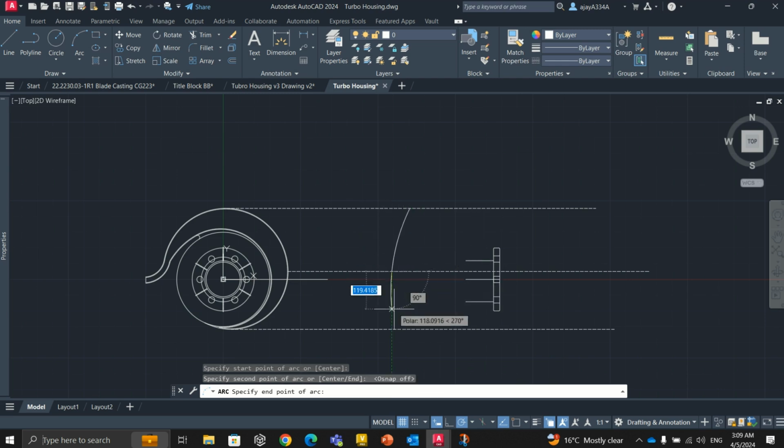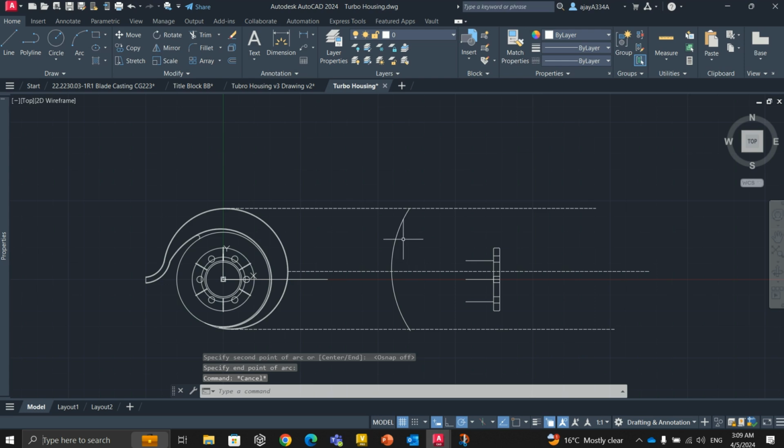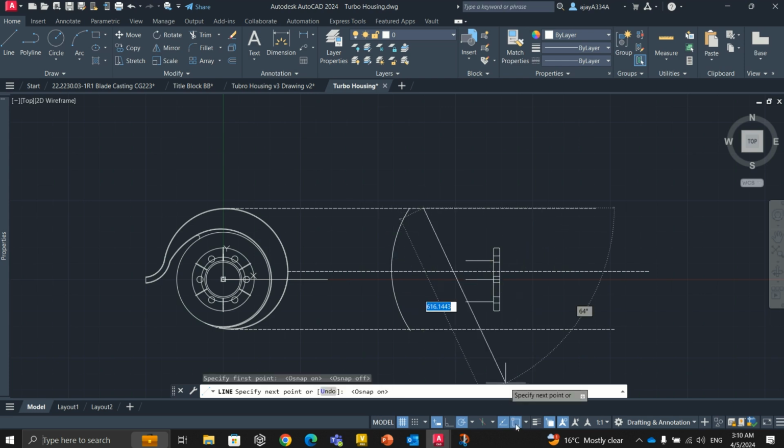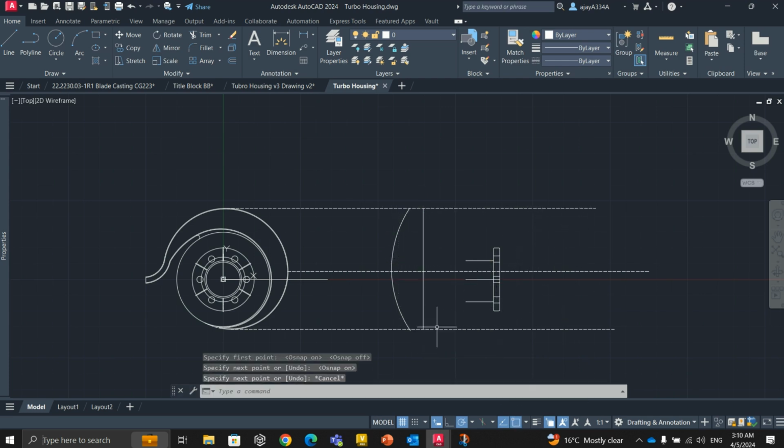And you need to now put that into the 2D drawing space manually, and that can be achieved by using construction lines, drawing from the flange ends. So in order for you to have the right dimensions on the side view as well as the top view and the front view. Now in 3 dimensions, what you see in your mind, you need to put on a 2D flat space, using the dimensions as well